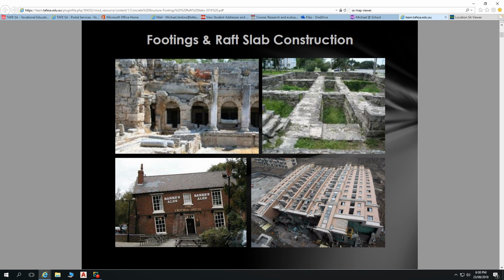We were talking about strip footings with brick plinths and suspended timber floors. Wind the clock back further to about 1920. We're talking about strip footings that are a combination of concrete and bluestone, things like that. Wind it back further, 1860 or so, it was large bluestone slabs with built elements over it. So not a very long timeline. We can see a very big progression in footing systems in a place like Adelaide. But predominantly, it's going to be raft slab footings.